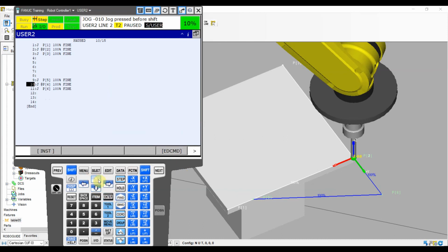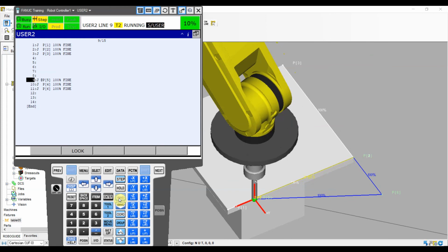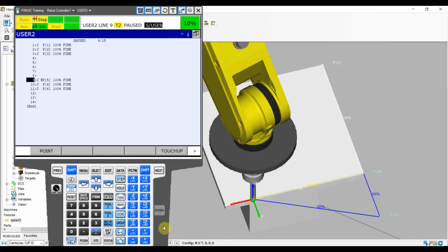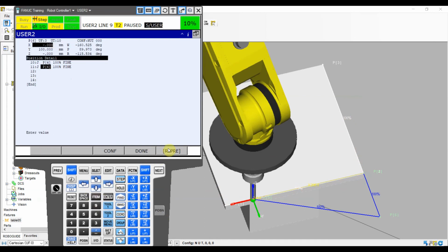Okay, so let's go to the beginning of our L that I created just from the points, guys. Again, just from the points. I didn't move the robot, but because I know the frame, I know the movement, guys. There you go. That's our first point, right? Now look where the robot will move. So we're drawing an L, guys. L, 200 millimeters and 100, so probably somewhere around here. Just let me make sure that I put the correct sign.